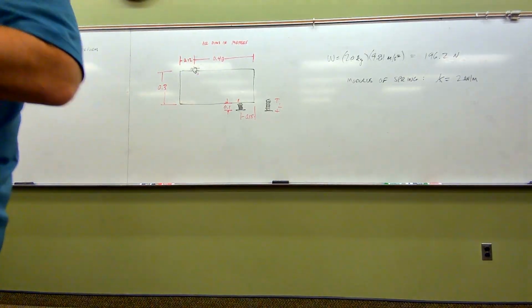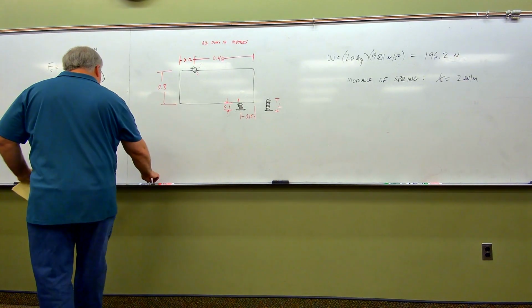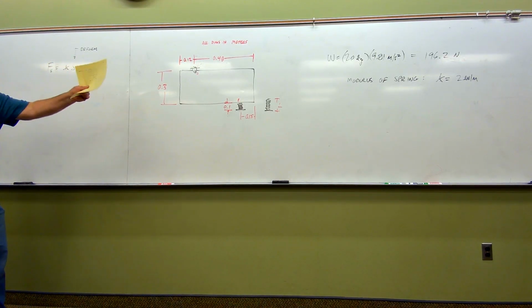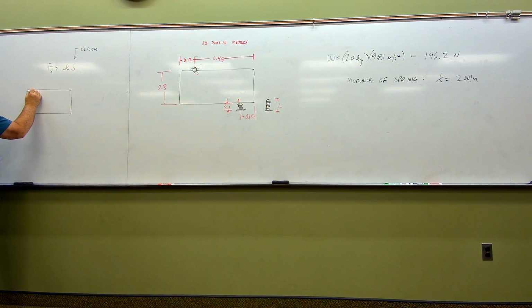It would be so legitimate for anybody to look at this and say, I don't even know where to start. On the other hand, let's always remember, when we're uncertain, let's draw a free body diagram. Free body diagrams are everything. So in this case, let's kick this whole thing off by drawing a free body diagram of our plate. We're going to draw the plate itself exactly as we're representing it here. We know there's a pinhole in the plate, maybe roughly right about there. We've got a pinhole in that plate.